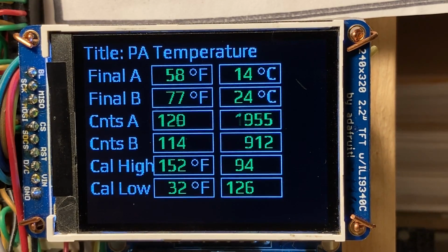But to do that, I had to come up with a way of having multiple parameters that could be dialed in. You insert your diode into whatever liquid you're measuring, let it sit a few seconds, and then you would have to hit a button, enter, to say take a snapshot of what the counts are at that moment to use that temperature.